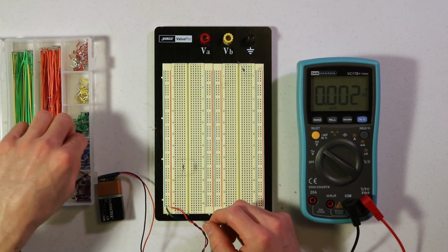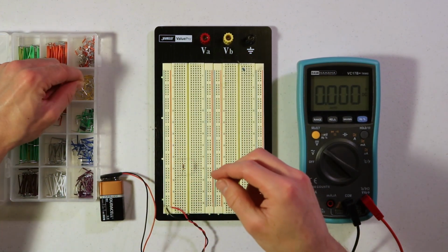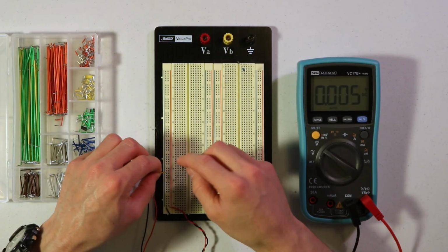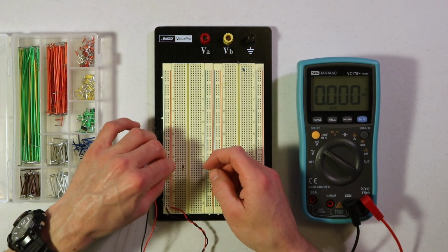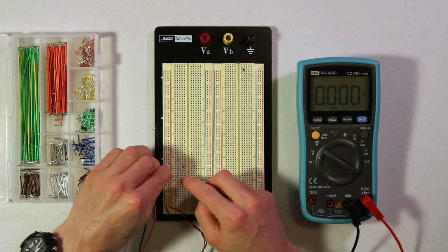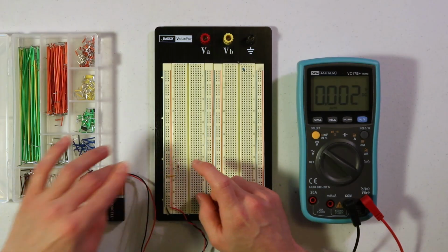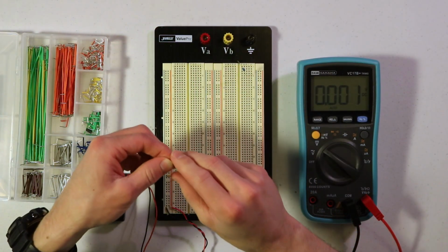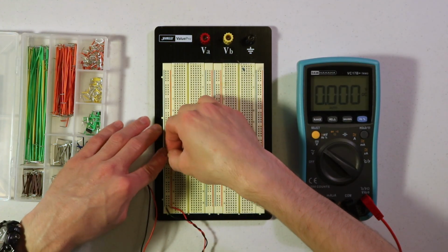Alright, so just grab some wires from your jumper wire kit and find some appropriately sized wires so that you can go from the power rail over to the resistor. So I want to have the black one going to the bottom here. Could be to the top, it doesn't matter since we've only got one thing in our circuit. But let's go ahead and connect to that. And then I'll get one of these ones. The colors for your kit are probably different than what I've got, but the same things will apply.